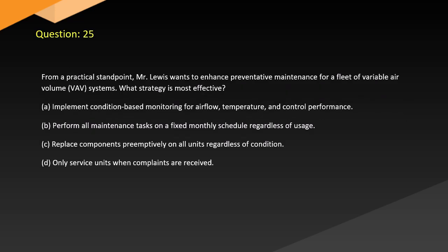Question 25. From a practical standpoint, Mr. Lewis wants to enhance preventative maintenance for a fleet of variable air volume valve systems. What strategy is most effective? A. Implement condition-based monitoring for airflow, temperature, and control performance. B. Perform all maintenance tasks on a fixed monthly schedule regardless of usage. C. Replace components preemptively on all units regardless of condition. D. Only service units when complaints are received.